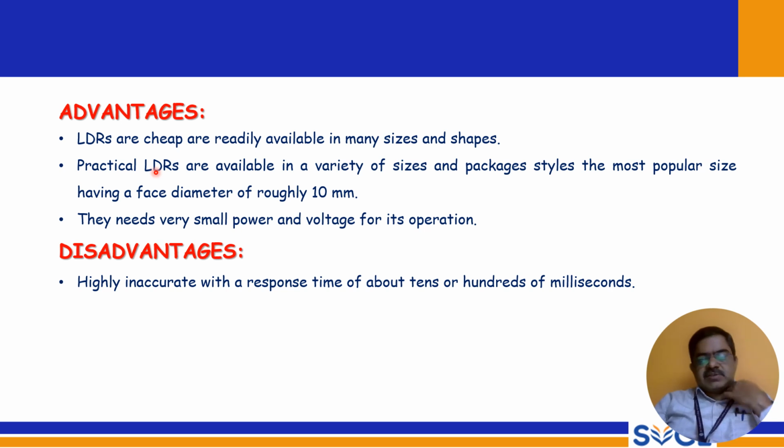So advantages of LDRs: LDRs are cheap and readily available in many sizes and shapes. Practical LDRs are available in a variety of sizes and package styles, and the most popular size has a face diameter of roughly 10 millimeters. They need very small power and voltage for their operation. Disadvantages: they are highly inaccurate, with a response time of about tens or hundreds of milliseconds. So this is the biggest drawback.